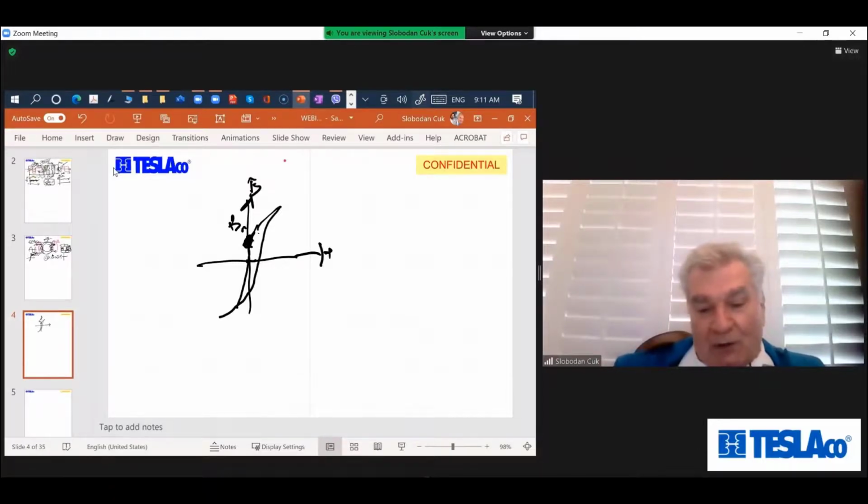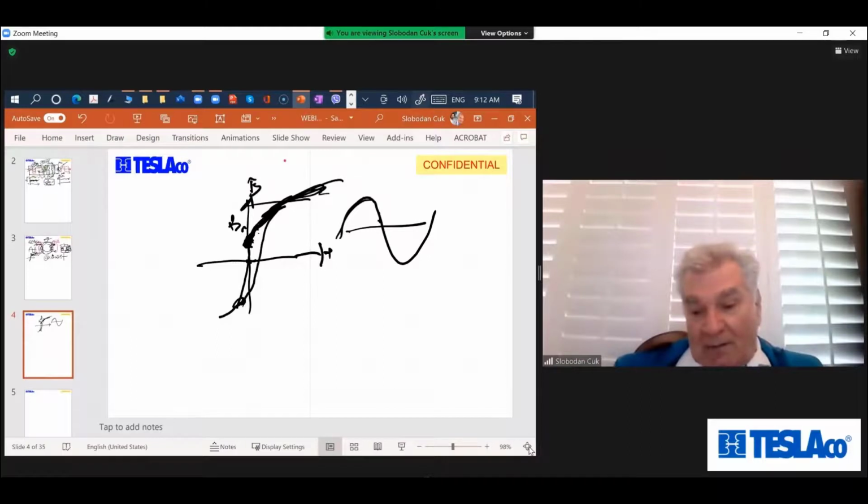So what happens when you start a converter, when you start a 60 Hz transformer, it may start from here. And because it didn't start from negative to positive, but started on a positive remnant magnetism, which is much closer to the saturation, in the first cycle you may actually go into saturation, because you start here rather than starting from there and going back and forth, right?